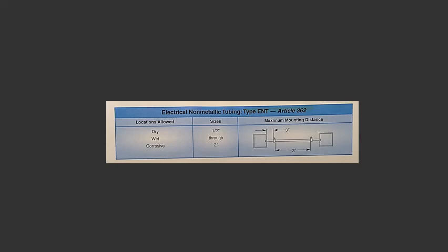Being lightweight and flexible, ENT is easy to handle. The various connectors, couplings, and fittings are attached with snap locks or plastic bonding cement. Installation varies and should be performed according to the manufacturer's instructions. See figure 4-25.